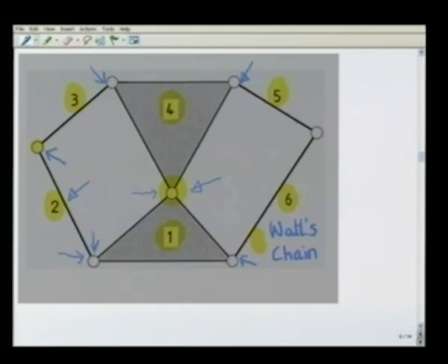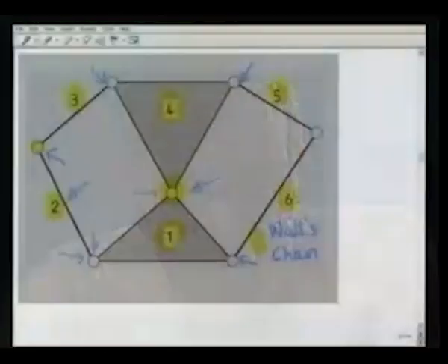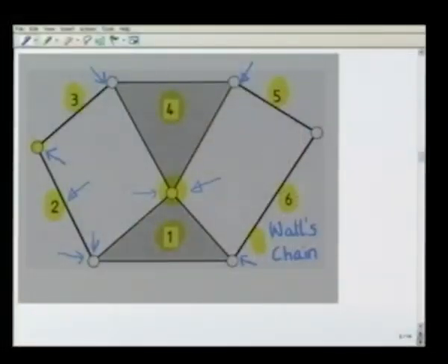So, from a Watt's chain, by kinematic inversion, that is depending on which link we hold fixed, we can get 2 different types of Watt's mechanism. One type of Watt's mechanism we can get by holding a binary link fixed, does not matter which one, 2, 3 or 5 and 6, because all of them are equivalent. And the second type of Watt's mechanism we can get by holding one of the ternary links, that is either 1 or 4, as fixed. We will now show a model of a 6-link Watt's mechanism where we will find that one of the binary links is held fixed.